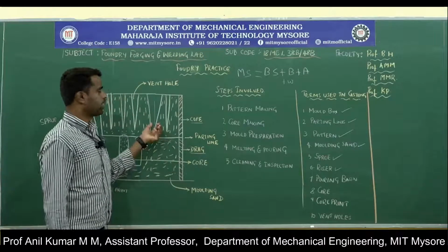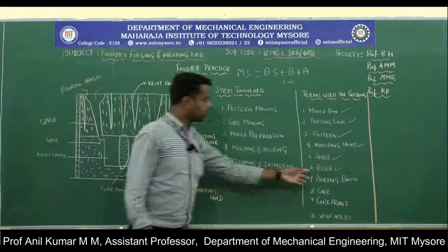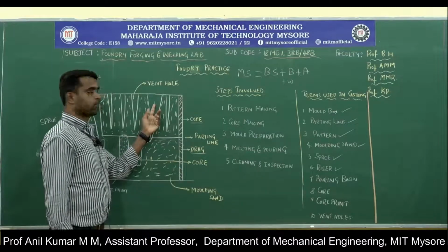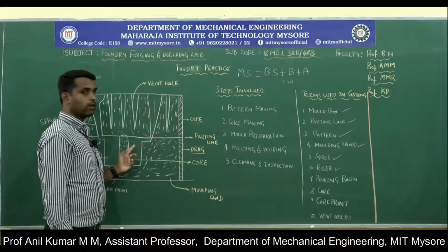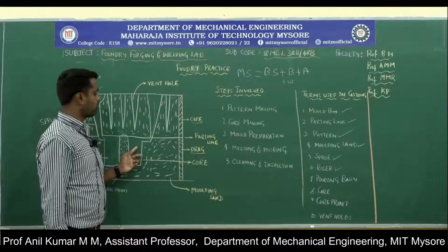Okay, that is called the riser. The riser is nothing but a vertical passage. It stores the molten metal while pouring and supplies the same molten metal into the mold cavity during solidification.